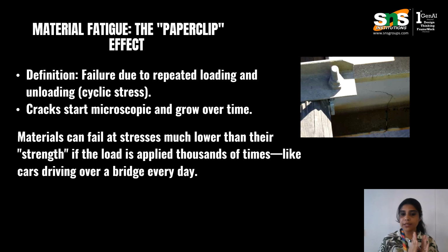Every time the load is applied, microscopic bonds in the metal break. These tiny cracks grow slowly, leaving beach marks that forensic engineers look for after a collapse. A material can be perfectly safe for a static load, but fail under a much smaller load if the load is applied a million times.